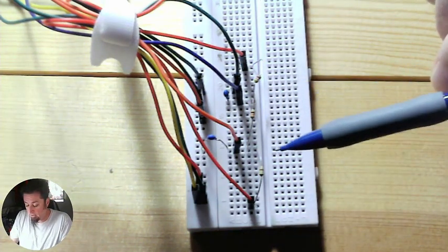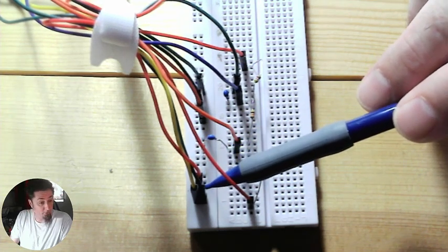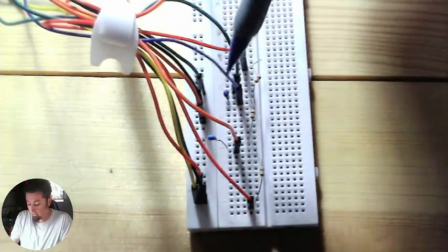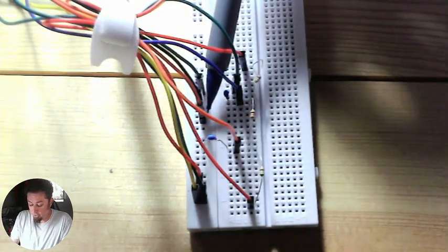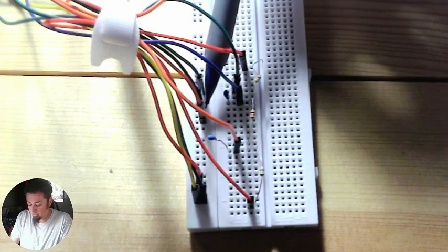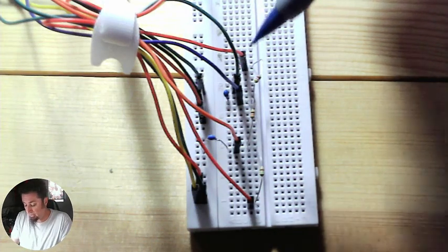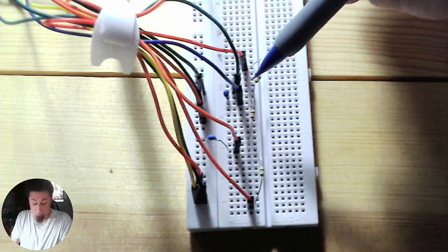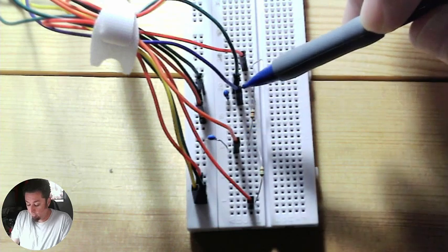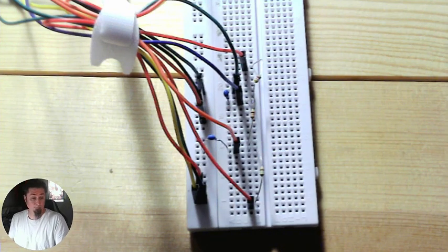Next, we'll look at our grounds. This is the ground for the bus right here, which supplies this whole bar all the way down here, which is also where we're putting channel 1 and channel 2 of our waveform reader for our Analog Discovery 3 into grounds over here. And this is also the ground for C2, this one right here. Then our two positive pins for the oscilloscope are here and here for right now. We'll move those along as we go.